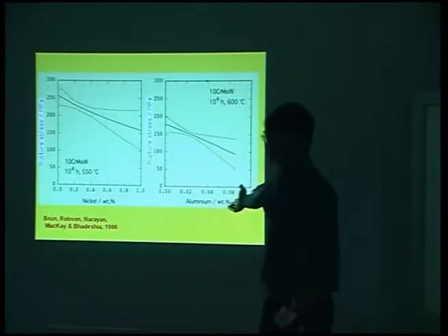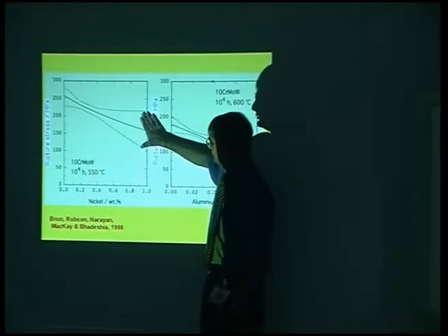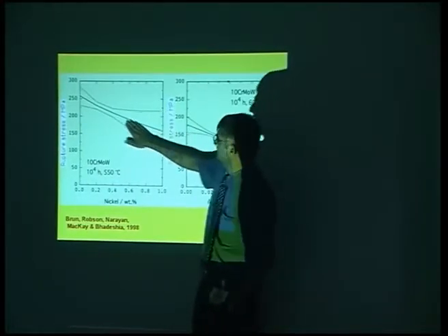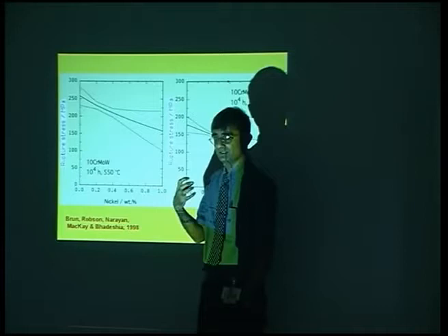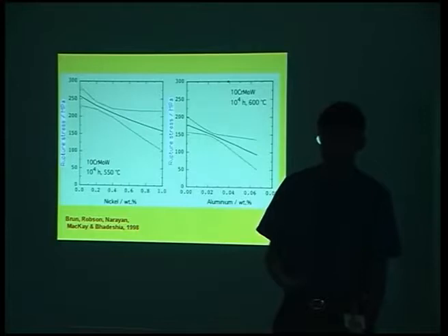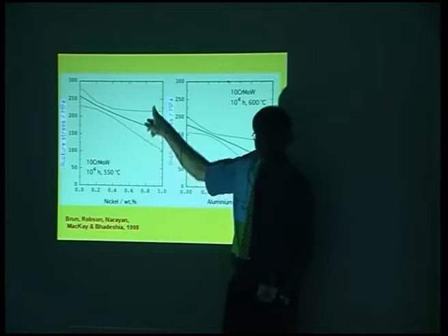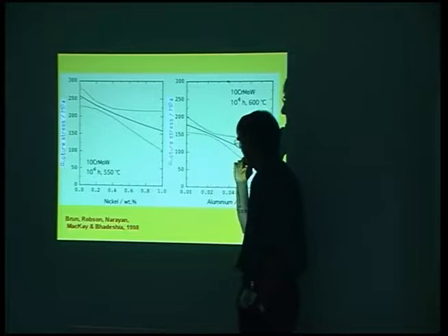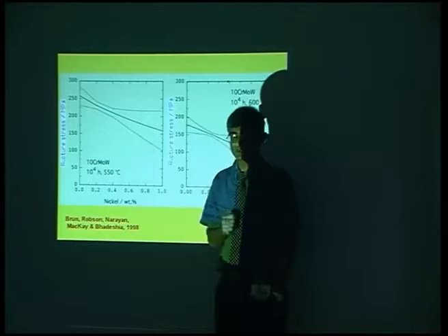So I showed you these calculations yesterday, and these are the uncertainties of modeling. Whenever you're making something new, you will get a large uncertainty. But if you notice that the trend, as a function of nickel, is justified because you know from metallurgy that nickel has a big effect on the coarsening rate of precipitates, then I would be happy to accept this result, even if the uncertainty is very large. But if I get a result which, as I increase the temperature, the rupture stress goes up, I would worry about that.